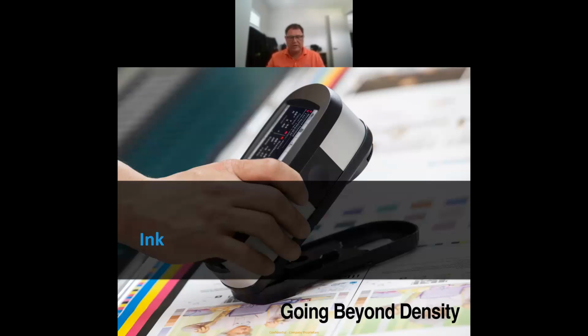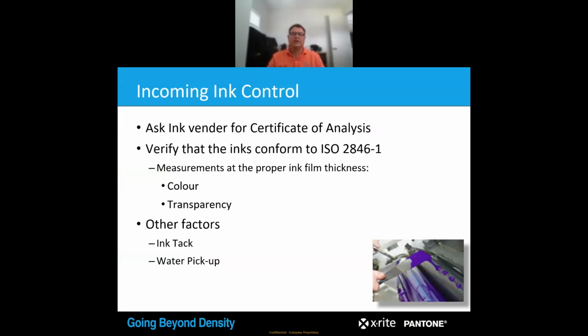Okay. Next important thing to think about controlling is ink. A lot of people within the printing industry take it as a given that the ink supplied to them is correct. The ink that I'm getting is correct, at a targeted density. If we go back to last week when we were talking about printing ink color, it's transparent, so you're getting white from the substrate. So the color being supplied to you of your CMYK inks or your spot color inks has to be correct at a targeted density. If you don't know what that density is, trying to achieve that color on press is almost impossible. If anything, it's going to be a very hit and miss process.